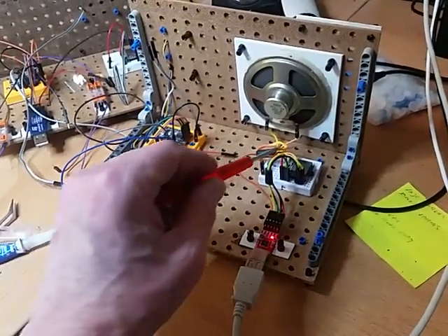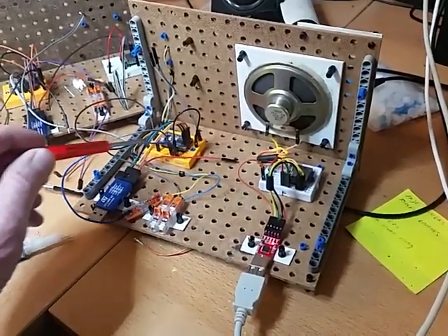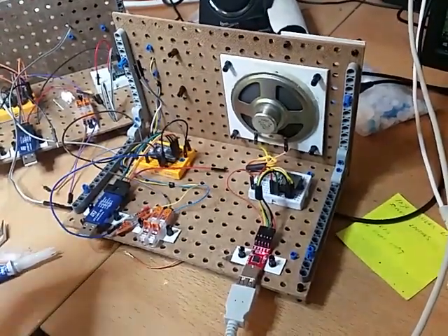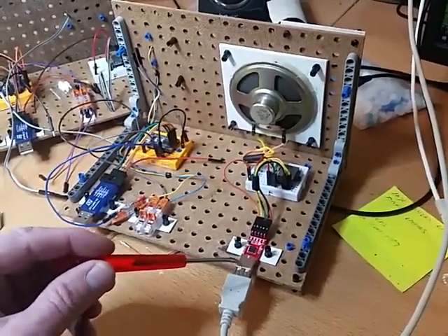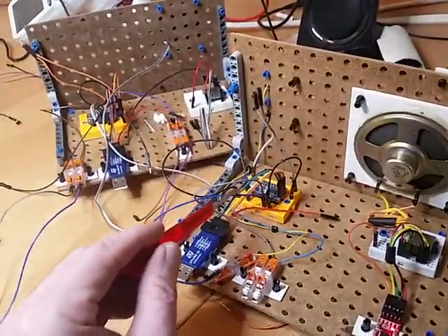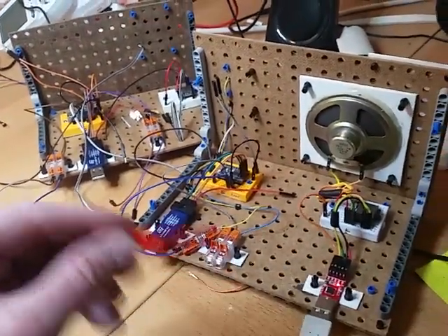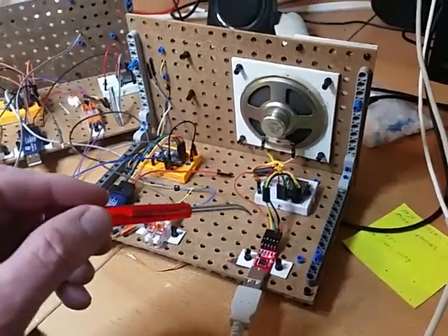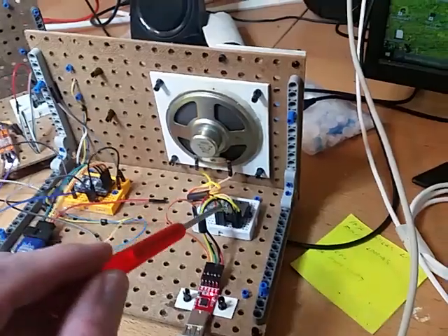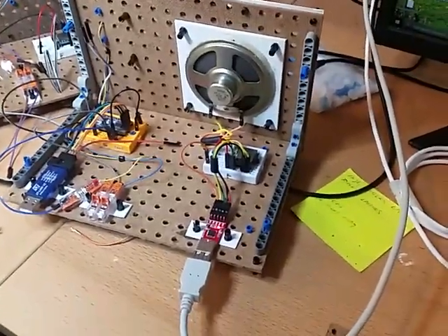Data is not going directly to the Mp3 player, but it's going to the microcontroller, and the microcontroller then controls the Mp3 player. So within hyperterminal, within my console, in the software of the STM microcontroller, I can make a program to control what WAV file is played on the SD card. But I will explain later if it all works.